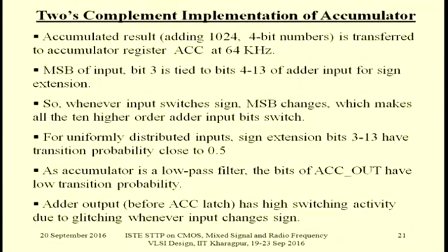Okay, so when the data changes from positive to negative, all the bits 4 to 13 should be 1, or when the data changes from negative to positive, all the bits 4 to 13 should be 0. Okay, so bit 3 is tied to bits 4 to 13 of the adder input for sign extension. Whenever the input changes, the MSB changes, which makes all the 10 higher-order bits switch. So that costs some power, sizable power.